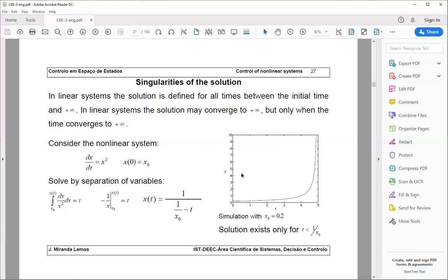But it's a naive state observer. Sometimes it works, sometimes it does not work. And even when it works, due to the nonlinearities, you can have such a phenomenon. And if you have such a phenomenon, the estimation error goes to infinity much faster than the controller is able to regulate the system.